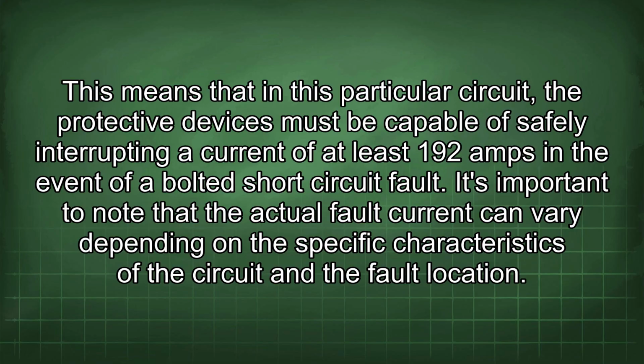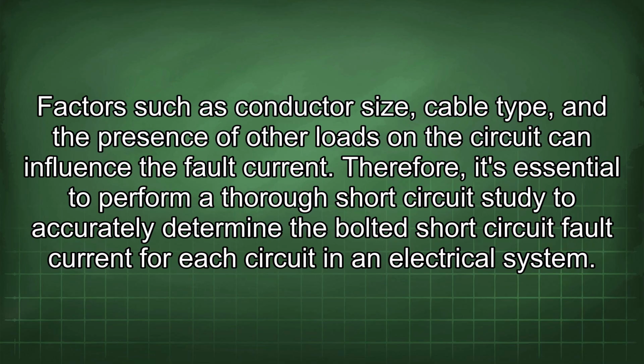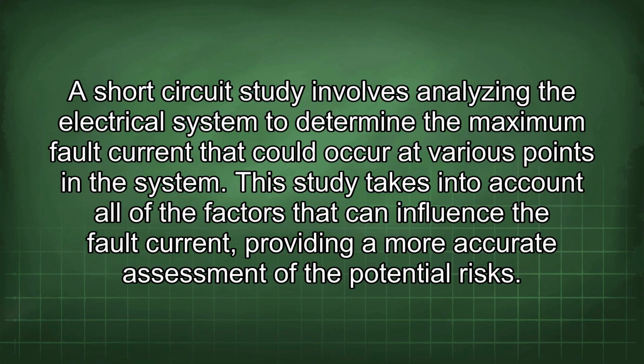It's important to note that the actual fault current can vary depending on the specific characteristics of the circuit and the fault location. Factors such as conductor size, cable type, and the presence of other loads on the circuit can influence the fault current. Therefore, it's essential to perform a thorough short circuit study to accurately determine the bolted short circuit fault current for each circuit in an electrical system. A short circuit study involves analyzing the electrical system to determine the maximum fault current that could occur at various points in the system. This study takes into account all of the factors that can influence the fault current, providing a more accurate assessment of the potential risks.